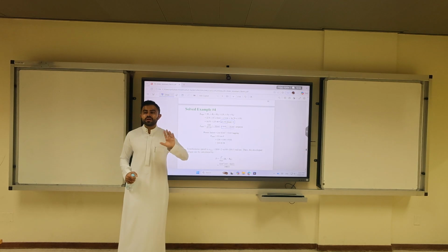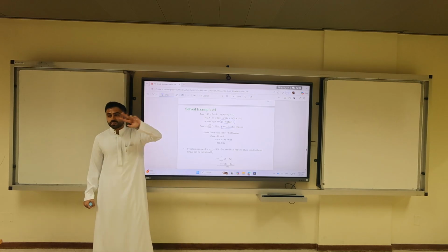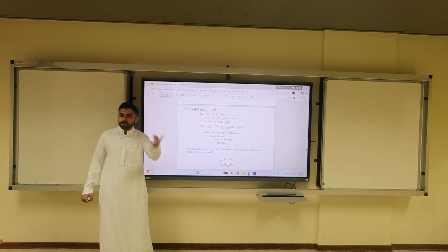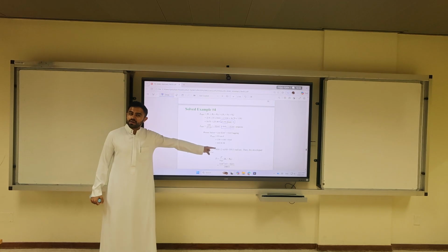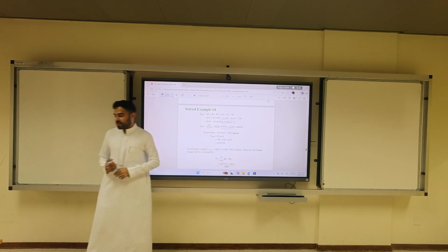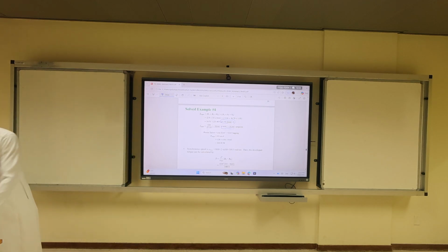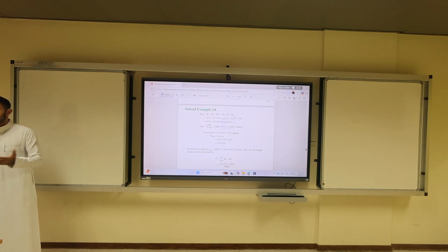So this is an induction motor. It means any future power calculation, if you multiply by S, the forward air gap, the backward air gap, has to be always less than this number. Okay? One common mistake is students usually have answers that are not realistic. Power factor larger than 1. For a motor, synchronous speed is smaller than the operating speed. This becomes a generator. Doesn't make any sense.